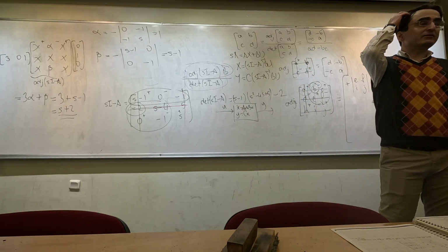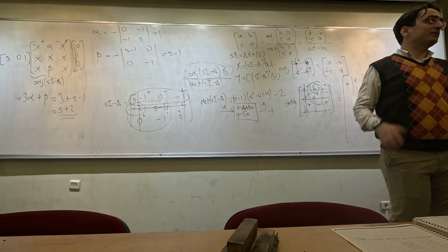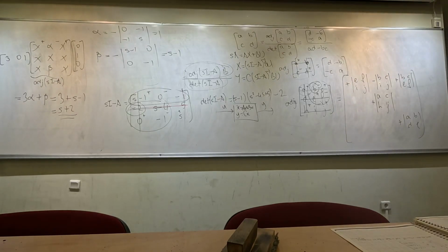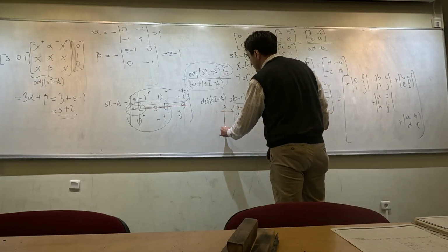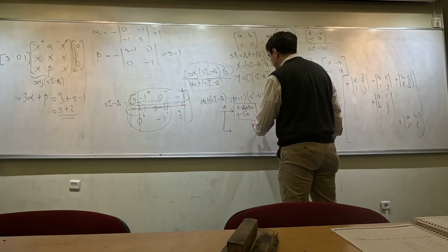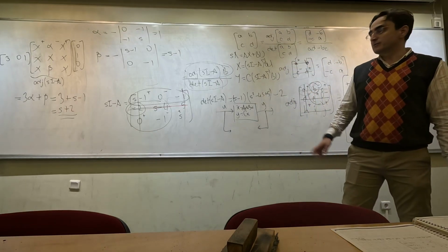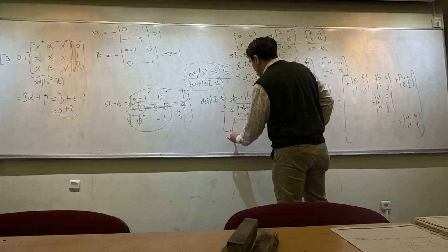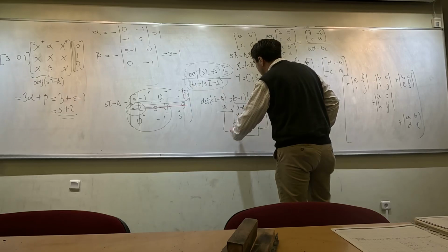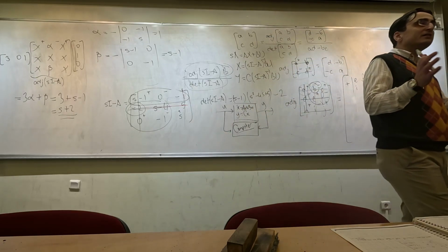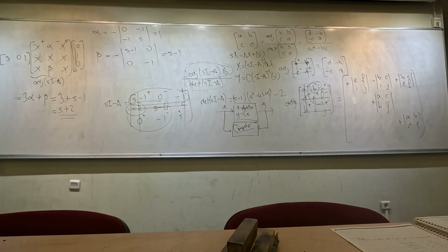For applying state feedback, I need the whole state, okay? But for getting the whole state, I need to measure them somehow. I really do not want to put additional sensors into my system. That is why sometimes we choose the observer method. That means that we measure only the input and the output of the control system, and we give it to a computer. In the computer, I can assume that I can solve any differential equation that I would like to solve, any linear differential equation.